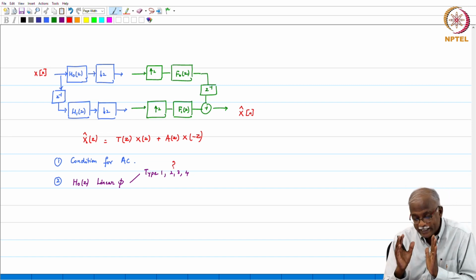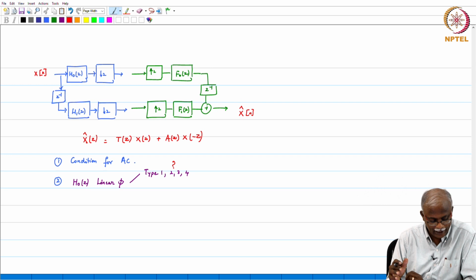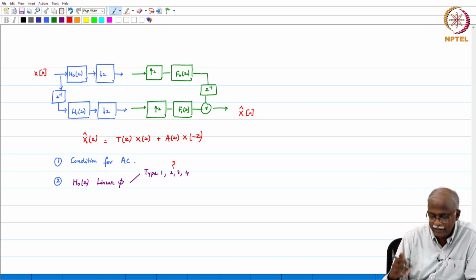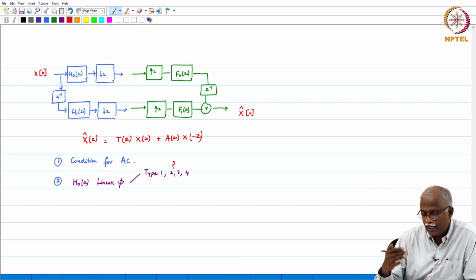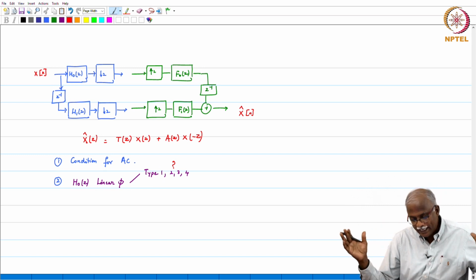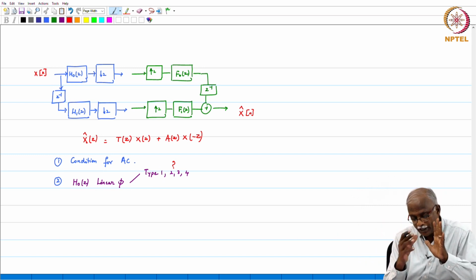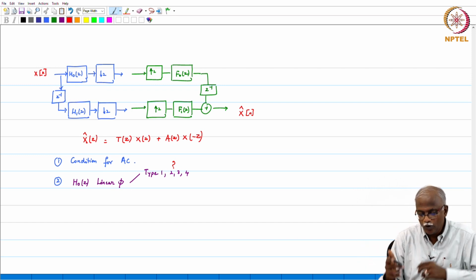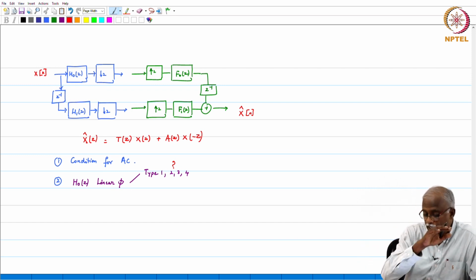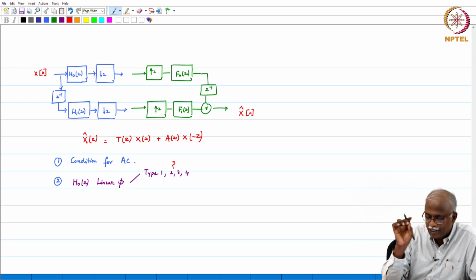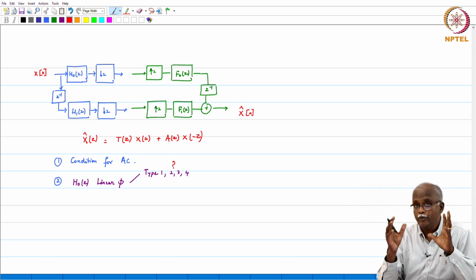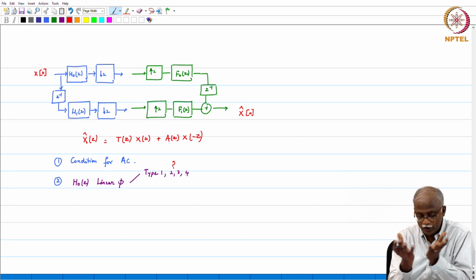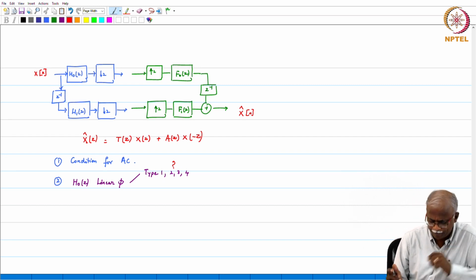And it is very instructive for you to go through this example and then try to answer the question: how is the linear phase property being utilized, how is the flatness constraint being achieved, and thereby overall a system which has no aliasing, no phase distortion, but only minimal amounts of magnitude distortion which is obtained because of the design methodology that we have used.